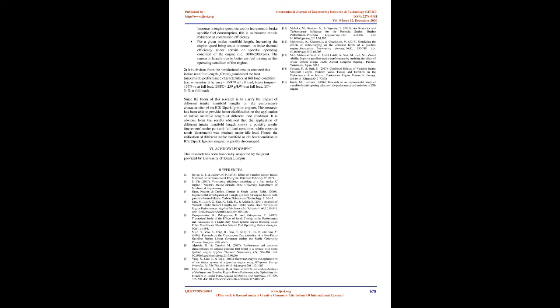2. It is obvious from the simulational results obtained that the intake manifold length of 60 mm guaranteed the best, maximum, performance characteristics at full load condition. I.e. volumetric efficiency equals 0.8979 at full load, brake torque equals 157 Nm at full load, BSFC equals 239 g/kWh at full load, BTE equals 34% at full load.